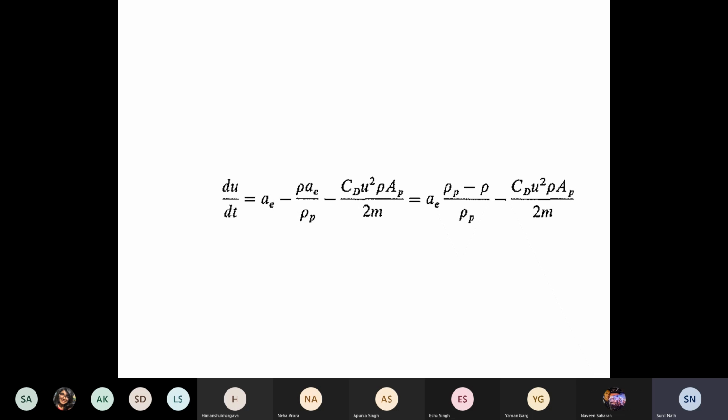But now we are going to put du/dt equal to 0. And now I would like you to solve for an arbitrary shape the maximal velocity that you can get first under gravity settling, and then, assuming the same approximation applies for centrifuges, I want you to derive the expression of constant terminal velocity. Not such a great approximation, but nonetheless, assuming that you can make those assumptions, constant maximal u, I want you to derive that maximum velocity for the centrifuge, and tell me what expression you get.